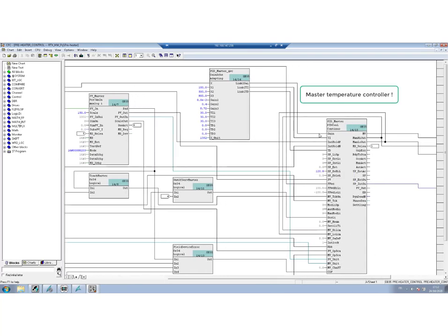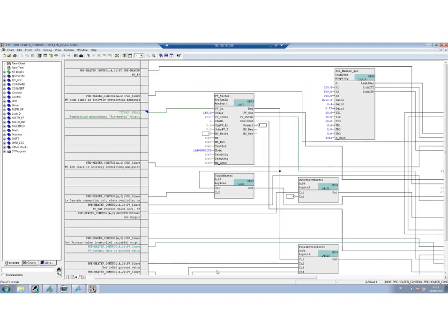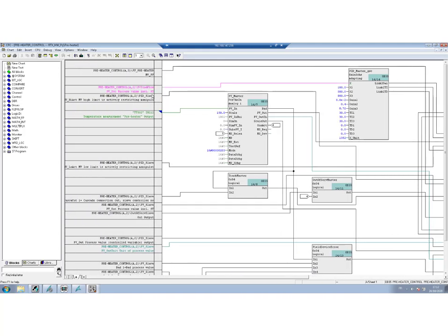But as you can see, the controller gain, the integral time constant, and the derivative time constant are coming from a block that is doing gain scheduling, right? So without a surprise, the scheduling variable here in this block X is the product flow, as you can see.